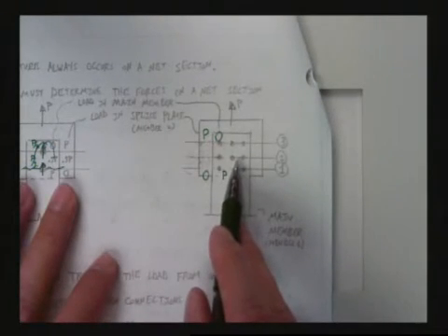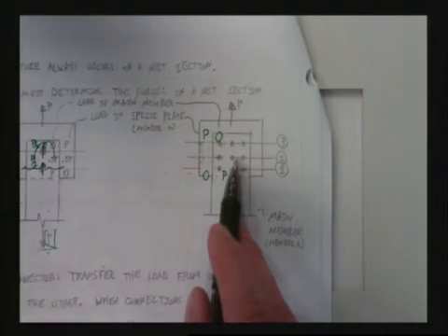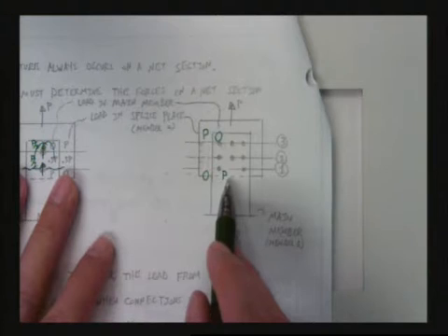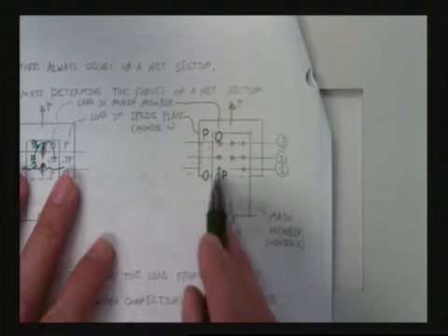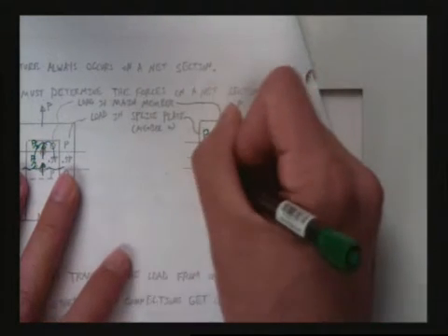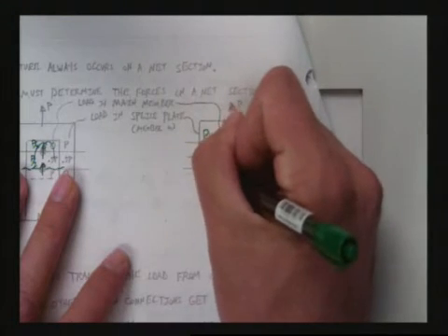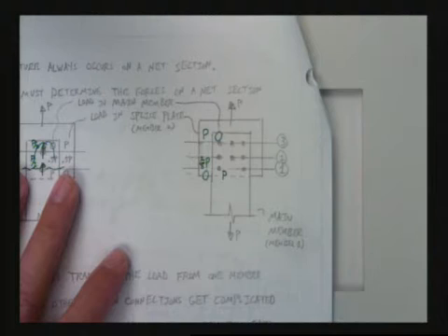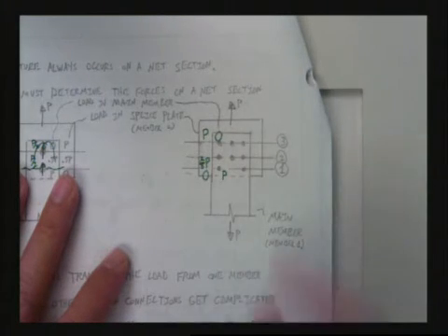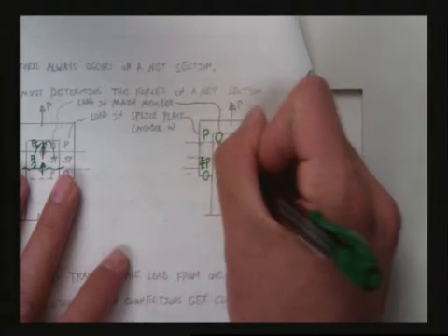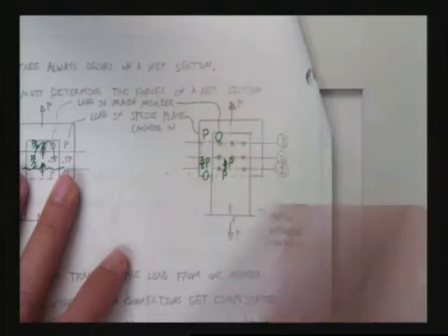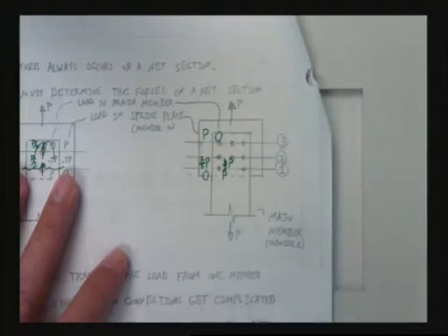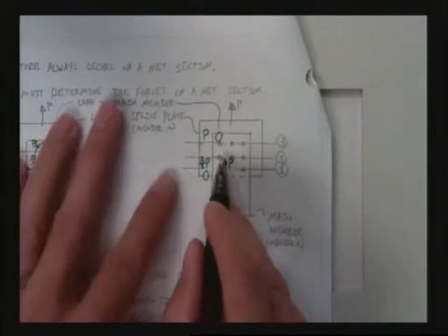We'd expect all 8 bolts to have P over 8 at the limit, right? Every bolt would have P over 8 on them. If I've taken 2 bolts out, that means 2 8ths have been given to the bottom, yes? And 6 8ths, P is still in that top plate. You with me? Okay? Let's go to the next one.